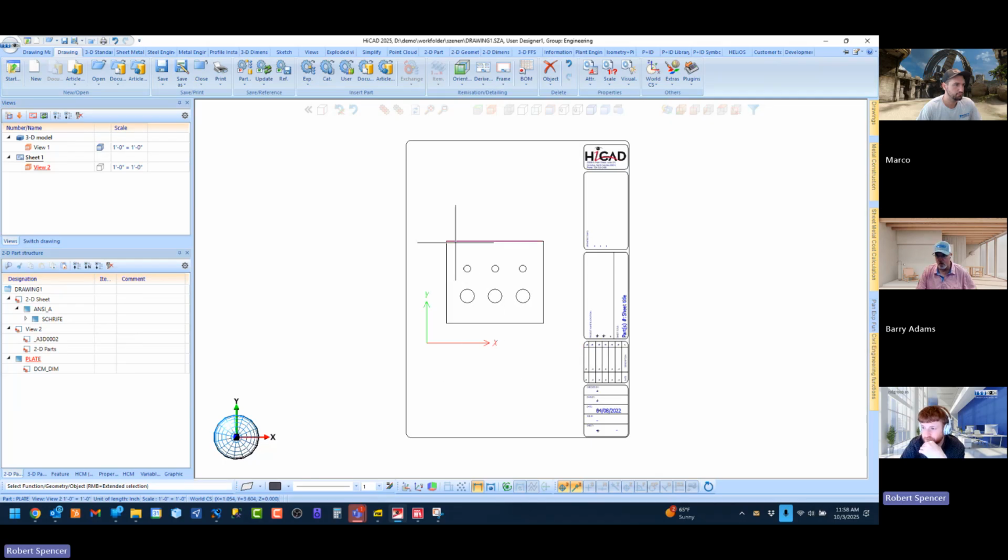So in 3D, this would be a view, and you could drag the view around. In 2D, we actually need to either move the frame or move the part. I tend to say moving the frame probably makes more sense because you might have put this part in a unique position. To move the frame,